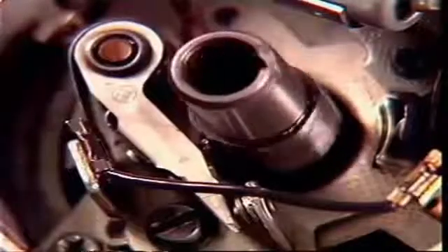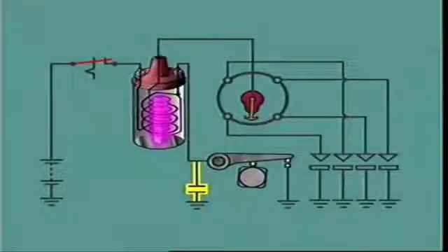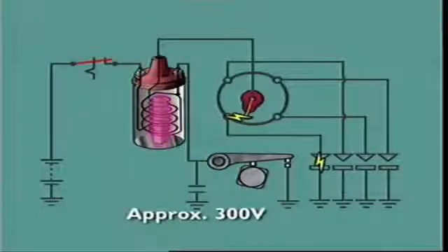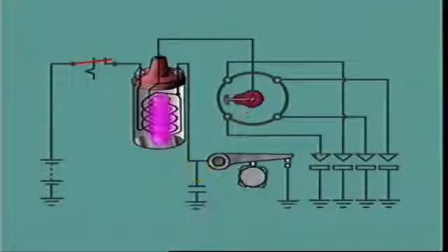Opening and closing the contact breaker switches the primary current off and on. When the contacts begin to separate, the primary current tends to flow on and produce an arc across the contacts. The capacitor absorbs this surge of inductive current by providing an alternative path in parallel with the opening contacts. The capacitor charges to the peak value of the primary winding voltage. By the time this has occurred, the gap between the contacts is too wide for a spark to discharge between them.